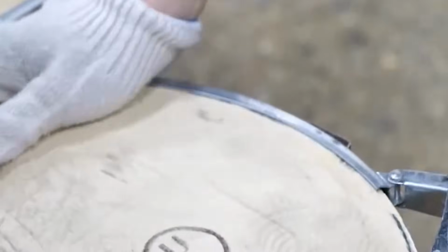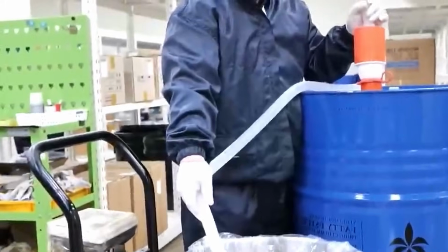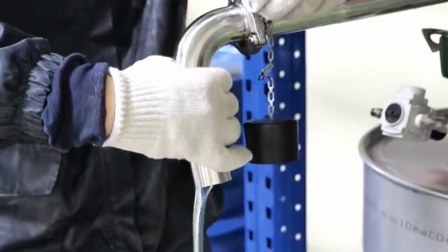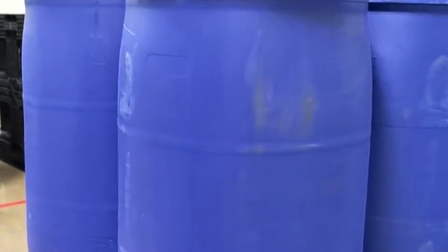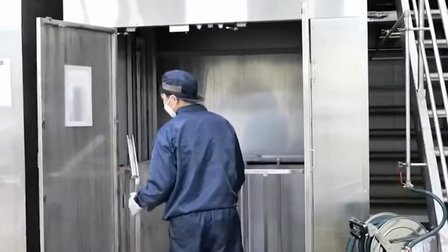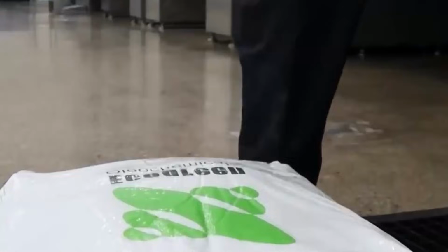After homogenization, the shampoo is transferred to a finishing tank. This tank is equipped with gentle agitation to maintain homogeneity while allowing the product to cool to filling temperature. Cooling is achieved via the vessel jacket using chilled water or ambient cooling loops. Final viscosity develops during this cooling phase, particularly for salt or polymer-thickened systems.